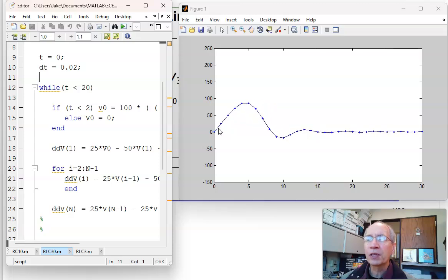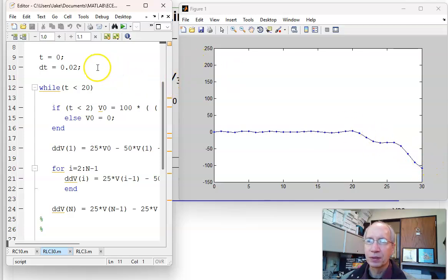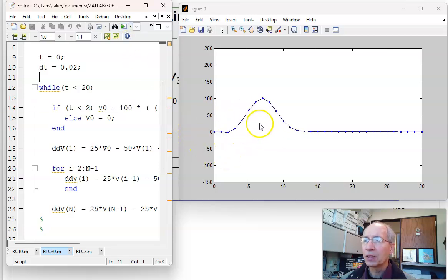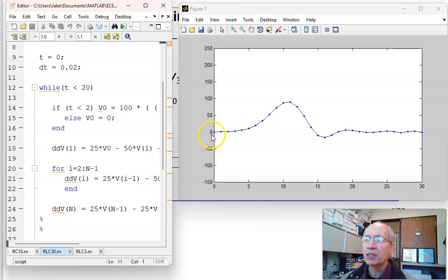Now if you notice, there's a thing called a reflection coefficient. When I launch the wave, when it hits the right-hand side, I get a plus reflection. So here's the negative wave going to the right. It hits the right wall, reflects. Let's try that again. I launch a wave. The wave travels down the transmission line, hits the right wall, and it reflects. That is a plus reflection. When I hit the left wall, it is anchored at 0. When this is anchored, I get a negative reflection.